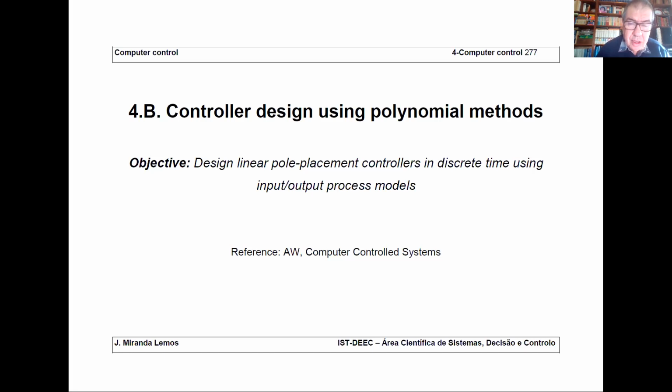Furthermore, before we were considering the feedback of the state. Actually, when you don't have access to the state, you use an observer. And the observer reconstructs the state or builds a state estimate based on output observations as well as input observations.